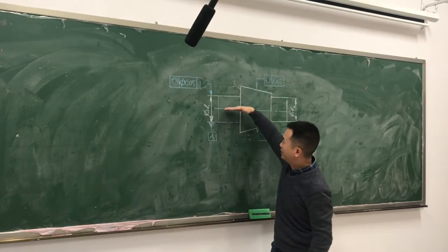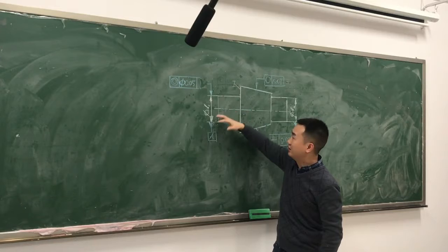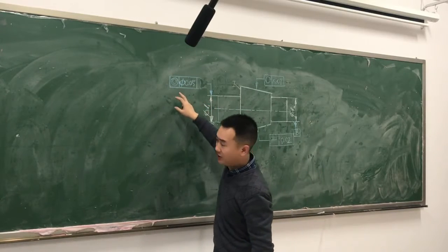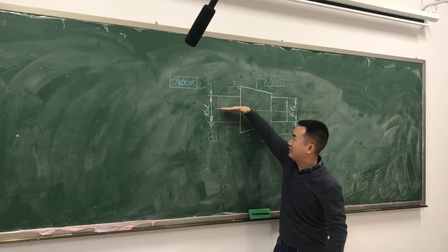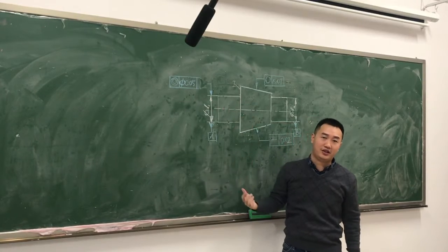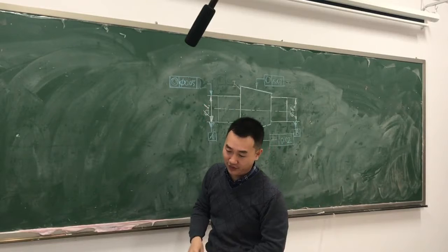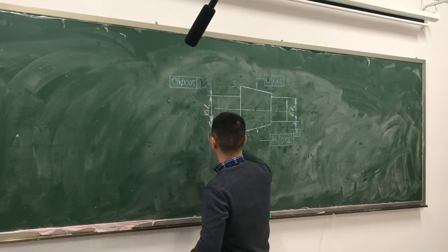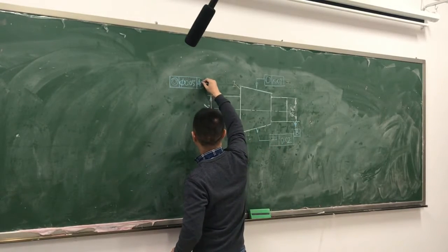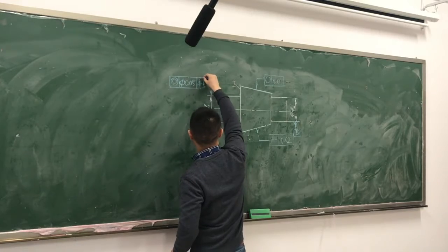In fact, the tolerance feature is the axis of the cylinder, and the concentricity limits the axis within a cylinder, right? Within a cylinder, so we should put a phi before it. And the datum is the common datum A and B.